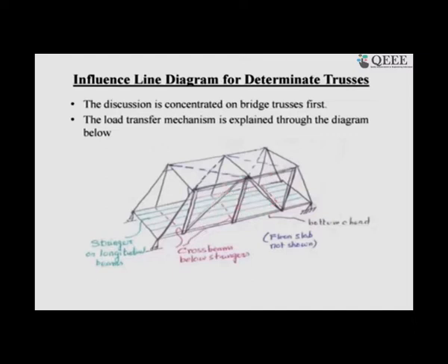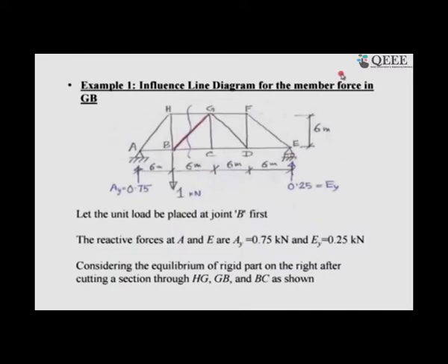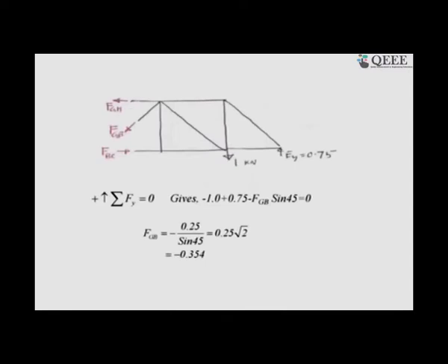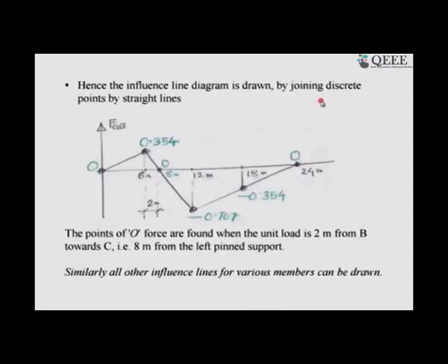Now, next, yes, so it is basically a truss solution with unit load at different joints, and the load moves on the bottom chord, and that is one of the examples for the truss. Yes, please. I think there is nothing basic, but we have solved probably one problem. Yeah, this is the shape of the influence line diagram for the truss, and we have also shown that the Muller-Breslau principle is equally applicable for truss.